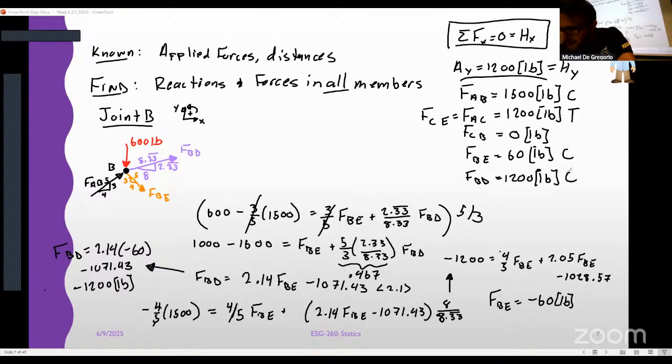We only need to solve one more, and that one's much easier. We're going to finish with joint D, because the only force left that we don't have before we go into symmetry is the force in member DE right down the middle, right? And remember, we can't call that one 0 because there's extra things that end up popping off it, but we're also going to prove it to you why we can't call it 0 in a second, right? So why wouldn't you use letter E?